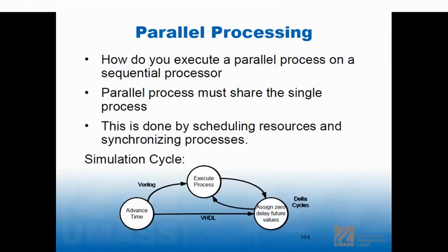The other time I see a delta time is if I have a combinational loop with no delay. Now, combinational loops are bad, right? It's not good design practice. I'll give you one example, but generally it's not good design practice. When you're doing your 0 delay simulations, your RTL simulations, that loop just keeps trying to change. So you have 2 inverters, for example, and this one changes, it causes this one to change and this one to change, and the delta time increases quickly.